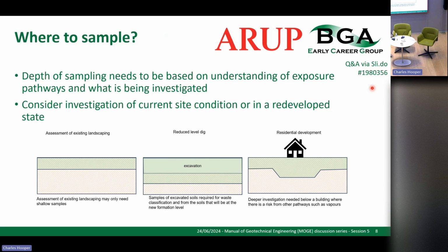Firstly, you need to know what's in that material you're going to remove. So we wanted to do a sort of waste classification, as we call it, to work out what landfill, or well, hopefully not a landfill, that material can go to when it's excavated. So you'd want to make sure that you're testing to the full depth of it.